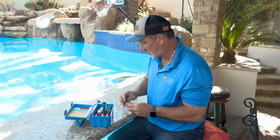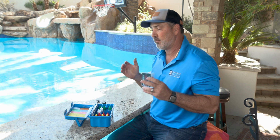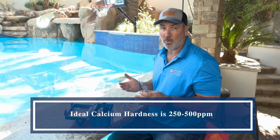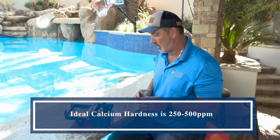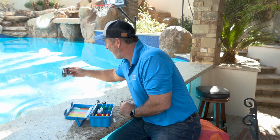So next we're going to go to calcium hardness. Now one of the common misconceptions is that you need to drain your pool every single year or every 2 years or every 3 years because your calcium gets too high. You can manage your pool properly with high levels of calcium, you just have to pay attention to the pH and the alkalinity. And we'll go into that a little bit on the LSI reading,